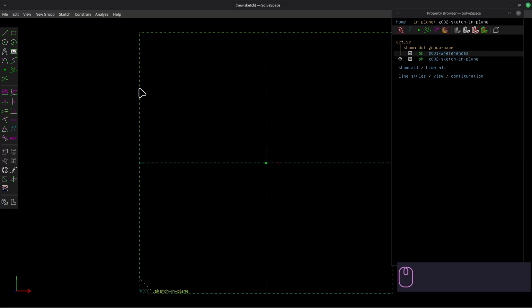The toolbar at the left has 3 main sections. The top section has drawing commands on lines, arcs, and so forth. The middle section has constraints, ways to control the drawing and specify lengths, that sort of thing. The bottom section has extrusion commands, how you create a 3-dimensional object from a 2-dimensional drawing. Remember about the toolbar that you can hover over a command to see what keyboard shortcut might exist. All the shortcut keys are shown in uppercase, but you don't need to press Shift unless that's stated explicitly, like